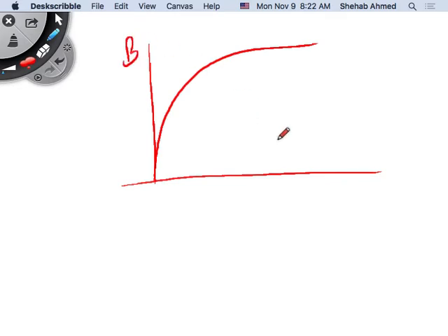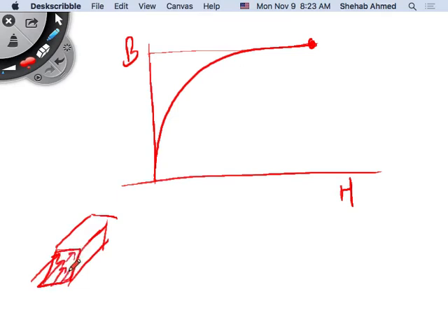For a component that had a BH curve that looked something like this, you wanted a certain magnetic flux in the core, right? So you have a core with a certain cross section. This cross section of the core will only allow a certain amount of flux lines in a certain area. If you provide more flux lines into the core than what the material can tolerate or withstand, so there's a maximum flux density that you can push into this material, right? If you push more than that, what are you doing?